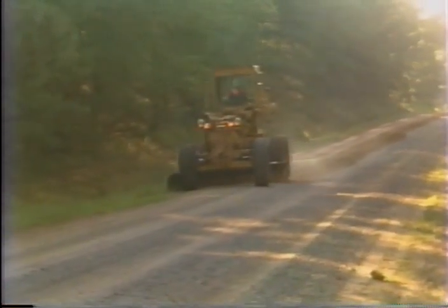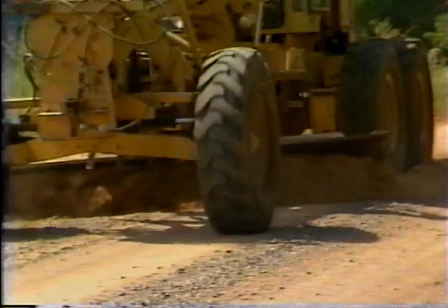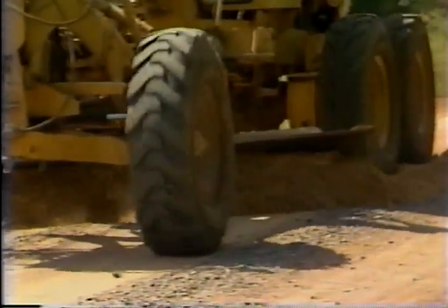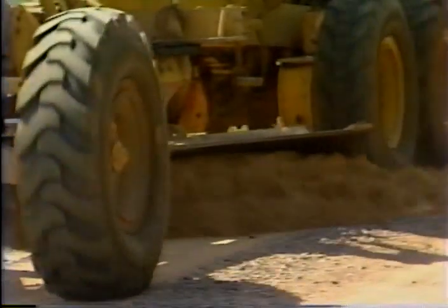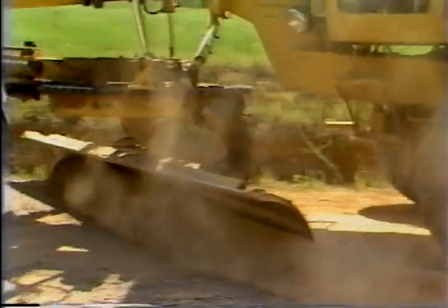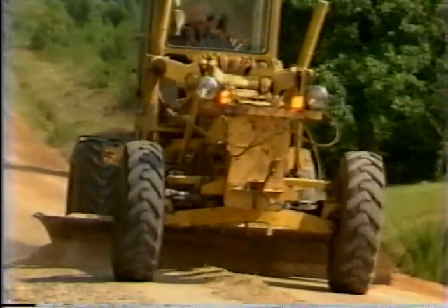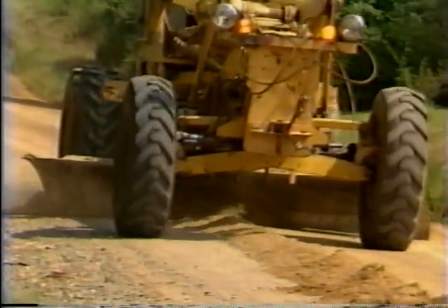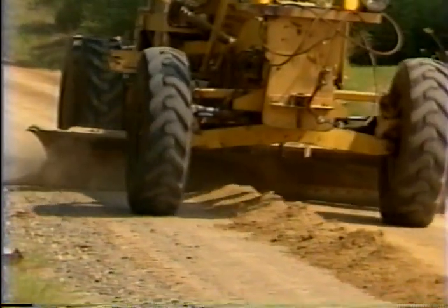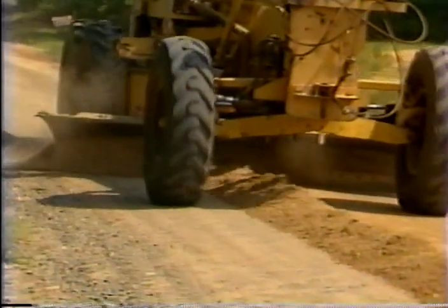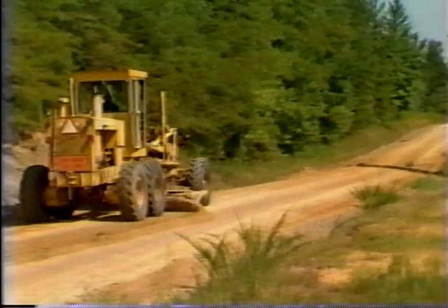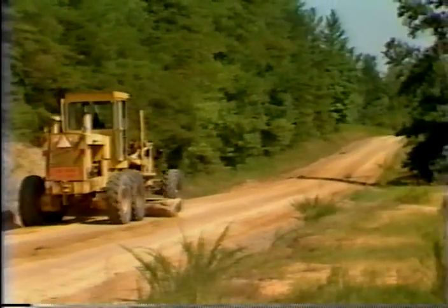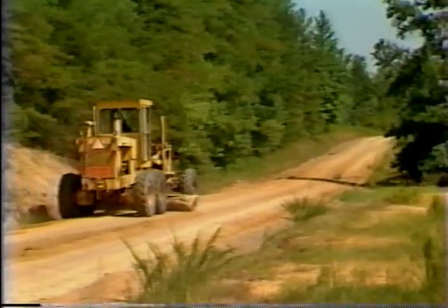The steps to be performed in routine machining are: number 1, the first pass of the motor grader pulls aggregate from the shoulder and windrows it at the center of the road. The blade creates dragging action and does not cut the crust of the road. Number 2, the second pass spreads aggregate across the opposite side at the proper slope. Number 3, the next routine machining cycle is performed in the opposite direction.